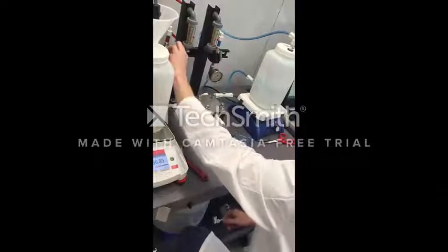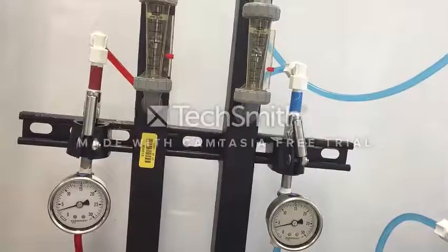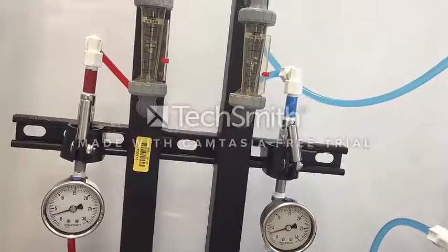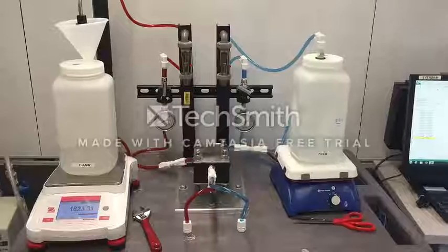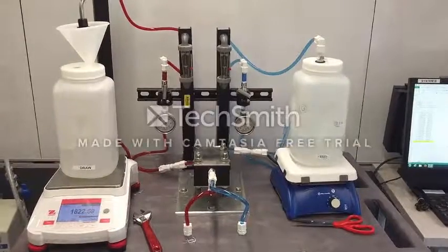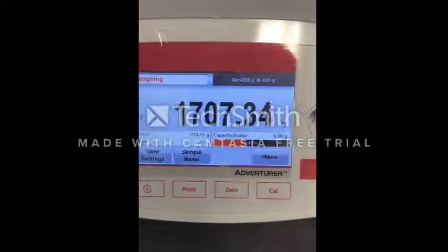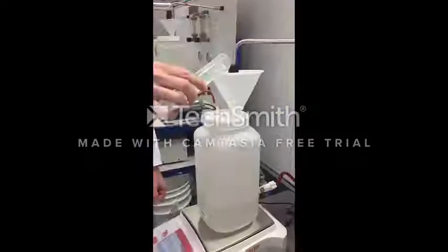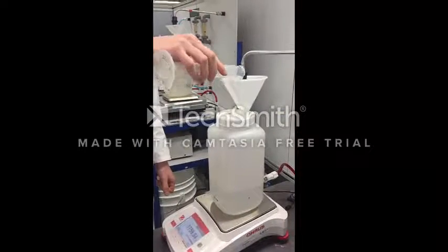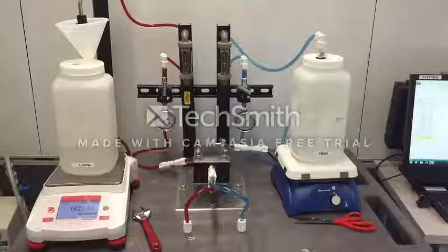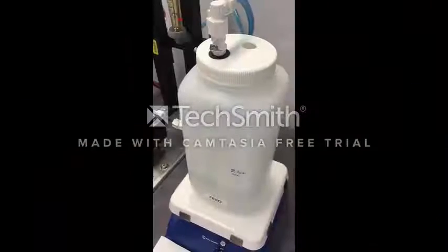Tighten the nuts and bolts to lock the membrane in place. Adjust the flow rates and pressures to the first desired testing parameters. Verify that both sides of the membrane are at identical conditions. Allow the system to equilibrate for 30 minutes, or until the mass change in the draw tank is less than 0.05 grams per minute. Add the first saltwater solution to bring the draw tank to a known concentration.